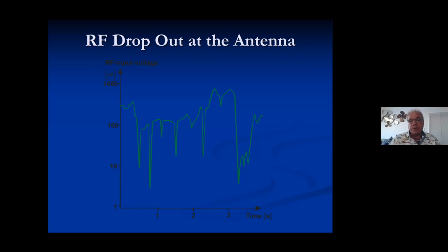What you're looking at is an actual level of voltage at the receiver antenna as a person wearing a body pack transmitter walks across stage. Now, in this case, you could see that's really good antenna placement, because the average line that you could see with those few dips in it is pretty good. The dynamic range of a wireless mic is really quite incredible. You could have your squelch threshold set as low as 1 or 2 microvolts and go all the way up to 1,000 microvolts. And that's what the front end of a wireless microphone could take. That's a lot of dynamic range. In this case, the average signal is over 100 microvolts, which is more than enough.